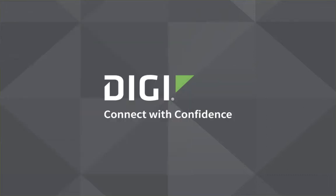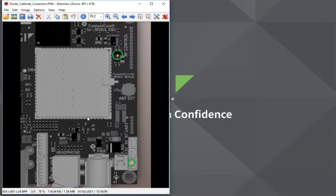The next thing is to connect our external Schottky diode. So the cathode needs to be connected to this point, which is exactly the same as the two cathodes of the Schottky diodes populated on the board. Now you have two options. You can connect only one Schottky diode and, in series, your external battery or power supply, which emulates the battery, or if you would like to also reuse the connector which is on the CC6UL SBC Pro, then you need to connect here also the anode of the Schottky diode.